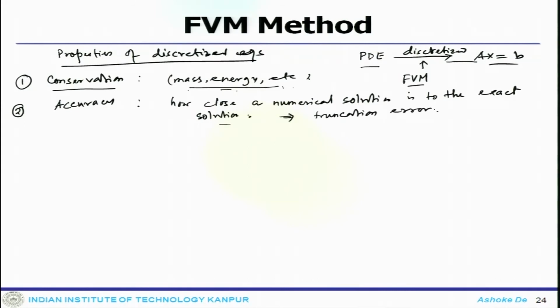Okay. And we have seen that when you do finite volume discretization, all your mean value, convective flux, diffusive flux, everything is of second order. So, the higher order term in the truncated expression will lead to the accuracy of the system. The more the higher order terms are retained in the expression, you get a higher order numerical scheme.